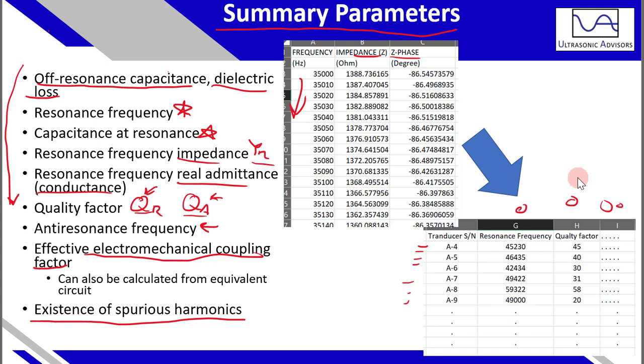We had described there to be a single resonance and anti-resonant frequency for your operation, but there may be multiple resonances or anti-resonances occurring, and that is due to multiple harmonics or operating modes occurring simultaneously, which can either be by design, where they theoretically are present, like two different types of modes operating at a similar frequency, or it's due to geometric tolerances, which can cause multiple modes to occur at slightly offset frequencies, which can significantly disturb the operation of your device.